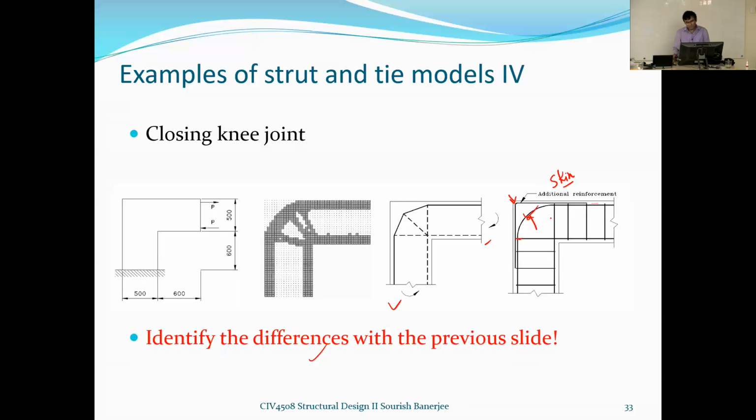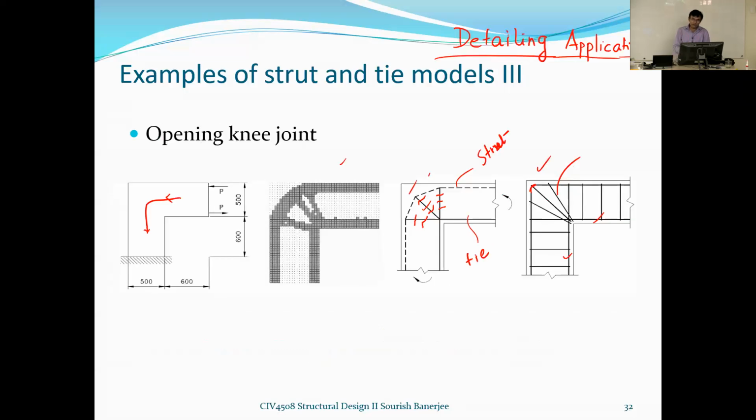And you can see the vertical reinforcement is going straight, and the horizontal reinforcement for the beam will extend up to this point. Okay. So it is good to compare with the previous slide, because in the previous slide, the outer column reinforcement was becoming directly the beam reinforcement. And then the beam bottom layer was just finishing here. Okay. And then we have these stirrups or the rings.